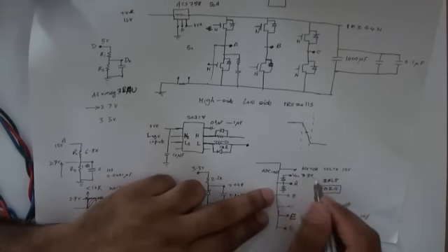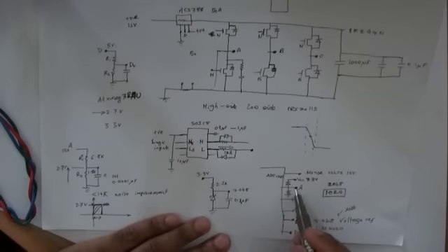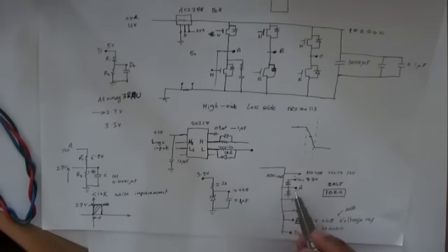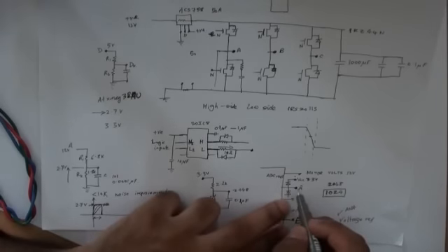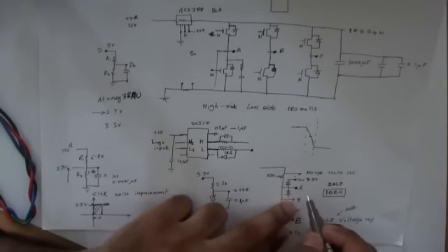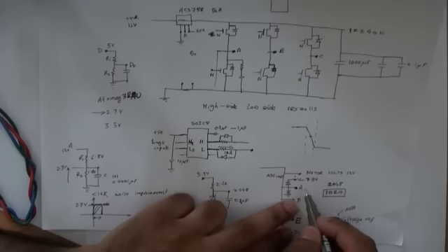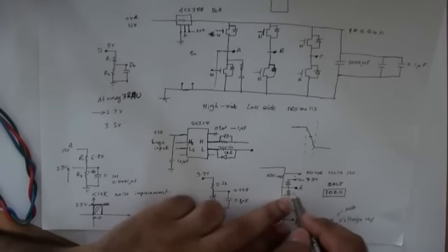So what this diode clamp does is, if this rail goes any higher than 3.3, then it will bring it down, and if this goes any lower than the ground, it will bring it up to ground. Well, it will short it out to the ground. So that way you're pretty much guaranteed that this input cannot be any lower than the ground. Well, it can be. It depends on the voltage drop across the diode.